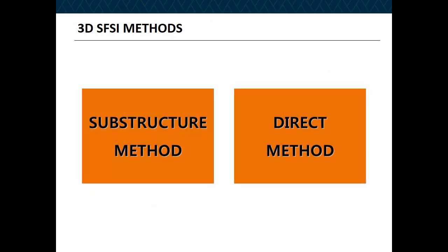So far we talked about how the boundary condition of the model is extremely important. Therefore, you need to be able to develop the correct boundary condition for the abutments and the correct boundary condition for the pile foundation. The boundary condition of the abutment, I showed you how it's developed, a very simple equation based on experimental data. And for the pile springs, I use Reese sand to develop the nonlinear pile springs.